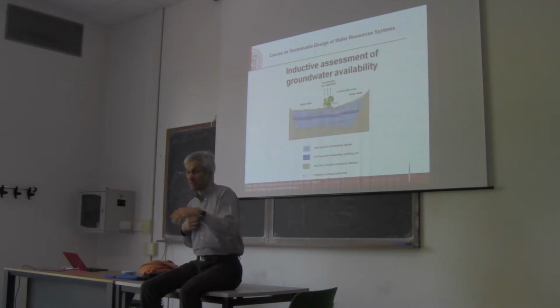If we see that even by taking water, the groundwater level doesn't change, this may mean that the recharge is higher than our withdrawal, and therefore we can continue getting water. So it's a sort of trial and error procedure.